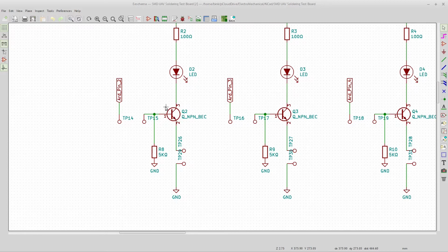Let's start with this. If I were to push this button, say it's a button right here where my cursor is, then it lets current flow through this device. So we have power coming in up at the top here, stopping right here, you push the button, and then it flows through. Great. Now, the pushing of said button is not done by your finger, it's done by Arduino pin 2 in this case.